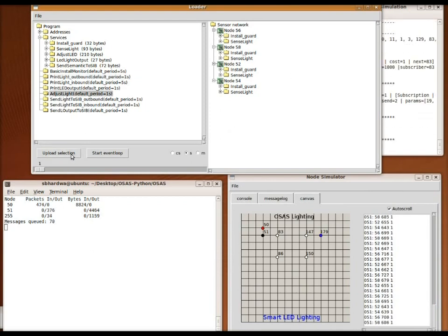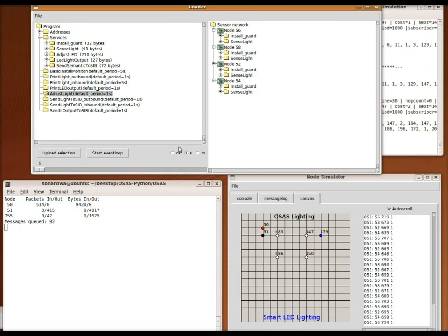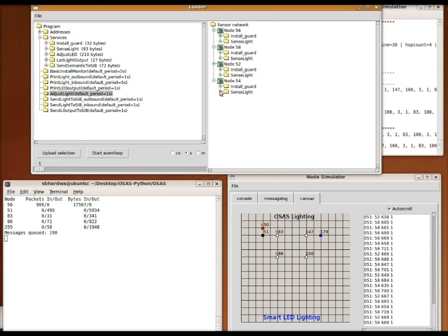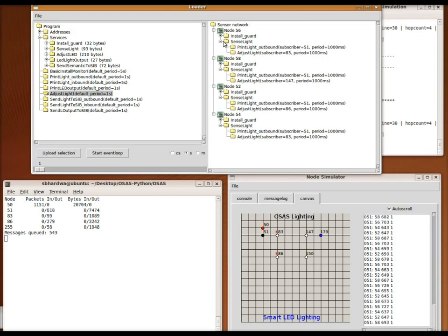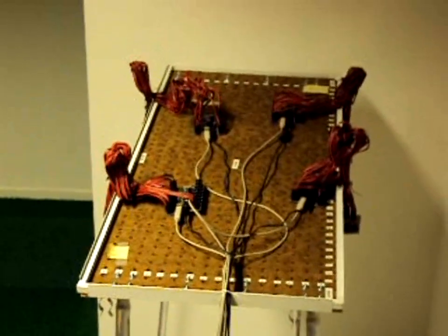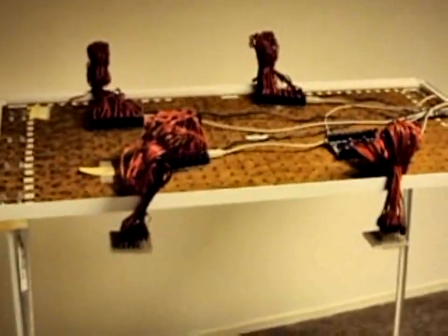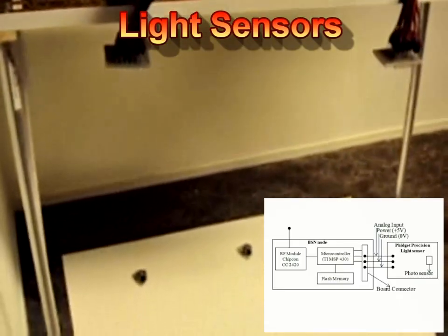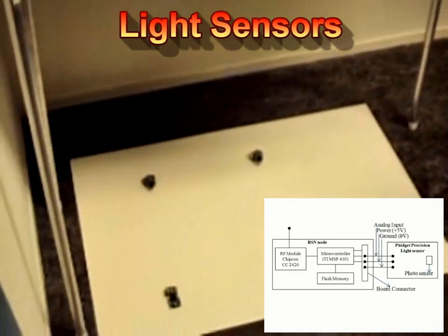The Light KP is connected with the wireless light sensor network based on the IEEE 802.15.4 protocol. It is also connected with a group of distributed LED luminaries over the USB interface. The light sensors are placed under each luminary, and the light intensity is reported to the Light KP periodically.